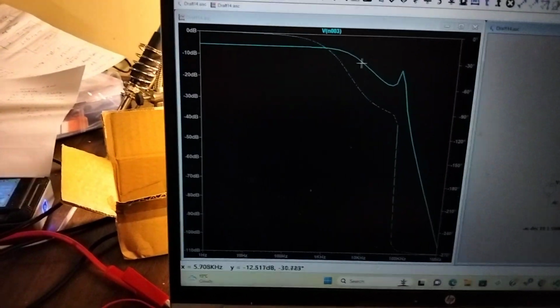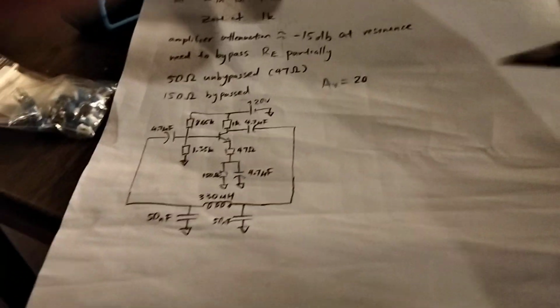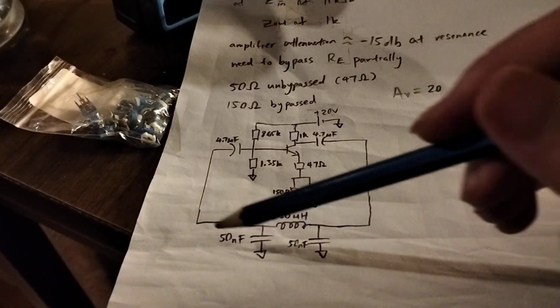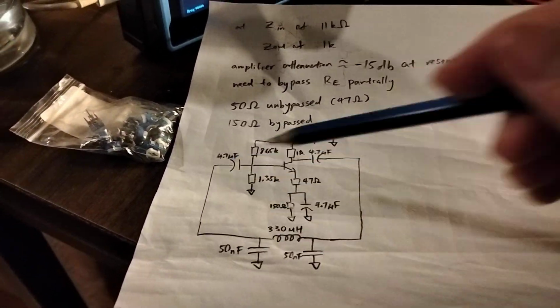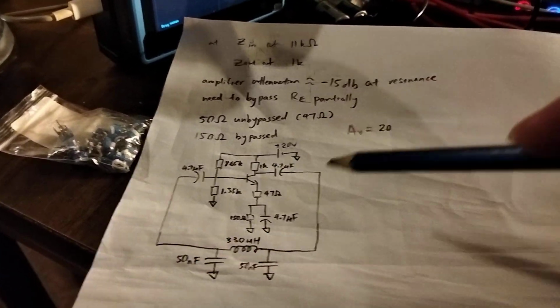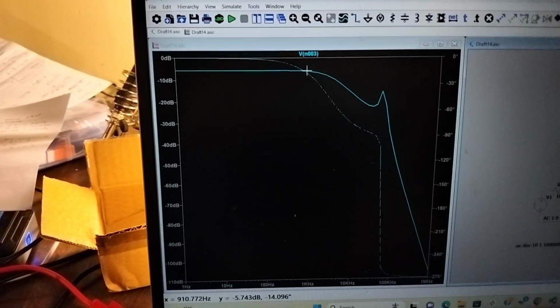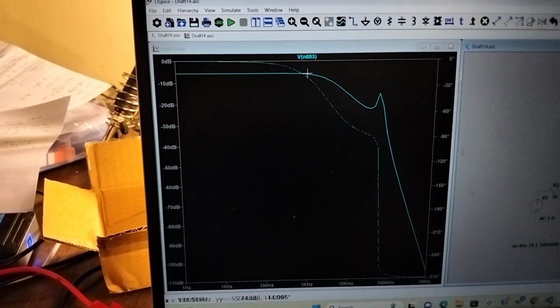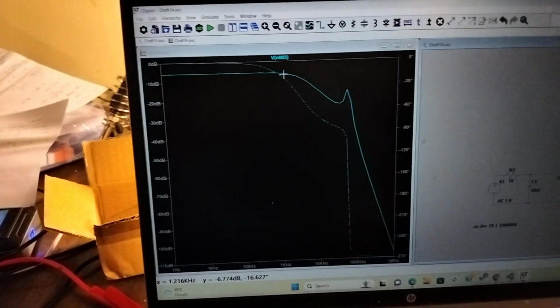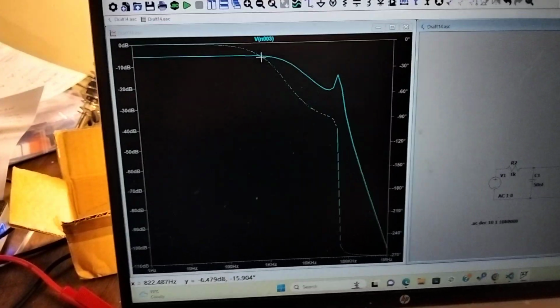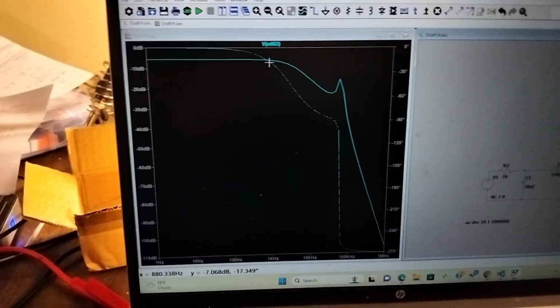So then, if it's a low pass filter, why are these frequencies not showing up? If it's a low pass filter, why are low frequencies not coming through here, getting amplified, and then getting added back up again? The reason is because even though the attenuation is smaller for lower frequencies, the phase shift is not 180.